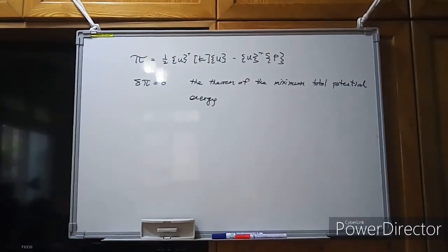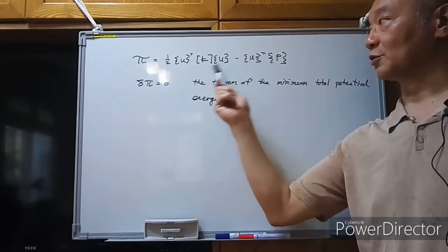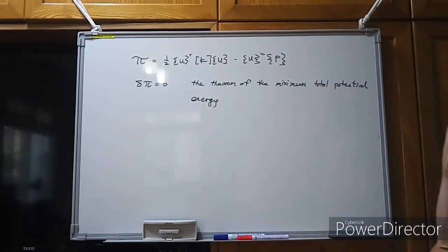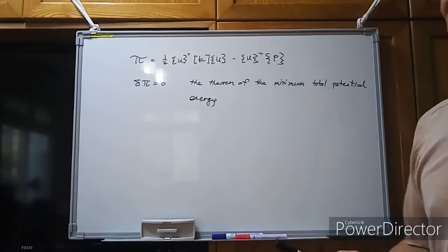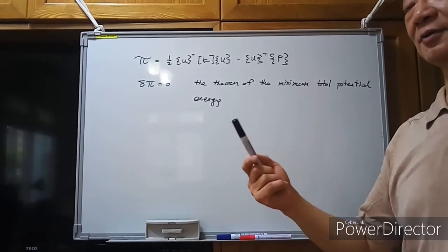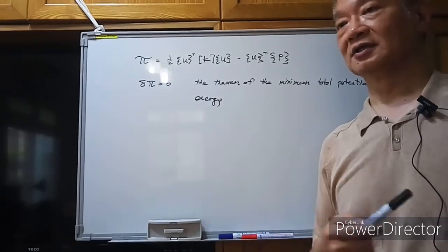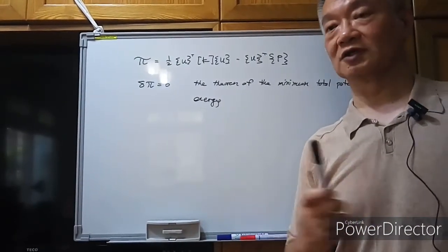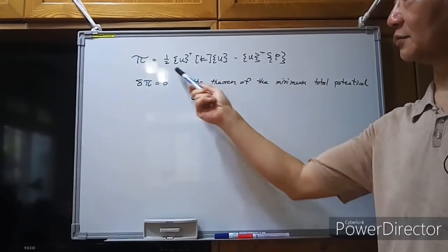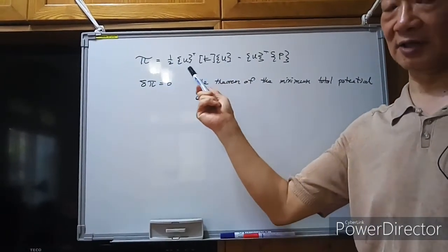And also the constitutive equations will be used when we calculate the K matrix, the stiffness matrix of the structure. When we calculate the strain energy, we need to multiply the strain by the stress, and the relationship between the stress and the strain is given by the constitutive equations. So the correct constitutive equations have been considered when we get the K matrix.